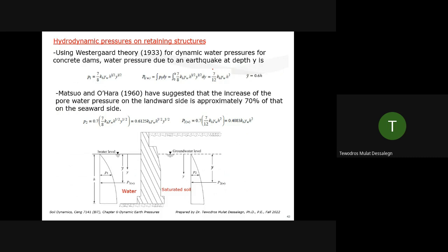We assume a sand soil, a silt soil, but there may be something else in it. So there is more complication. But these are simpler approaches. People try to use larger accelerations to be conservative. But when you do that, there is some penalty also. You may need more reinforcement, more section for the wall. So it gets uneconomical. If you want to be more economical, then you have to invest in the analysis, spend more time, a few days to few weeks, to analyze and design it properly.